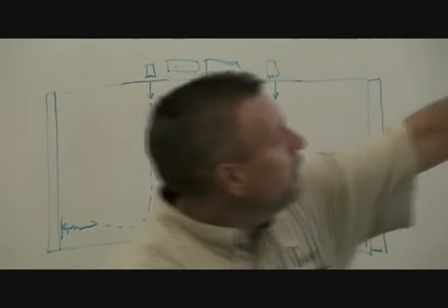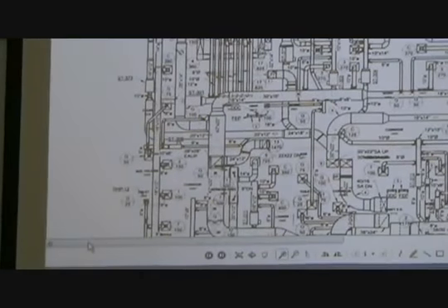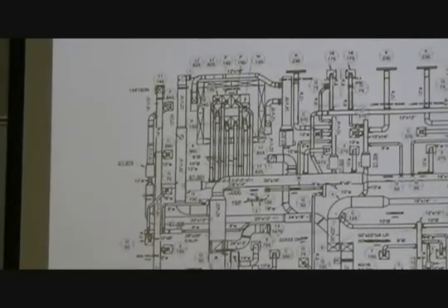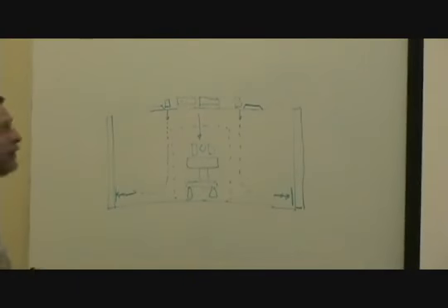And what they've done, they've got some type of sterile diffuser shown around that bed and around the light fixtures. There's another thing you have to coordinate with. There's generally a light fixture that wraps that room all the way around. I guess they've got their sterile diffusers inside the light fixtures. And hopefully there's a filter right there, but of course you got HEPA filters or 90% filters in the unit, but ductwork's not 100% clean, not sterile.